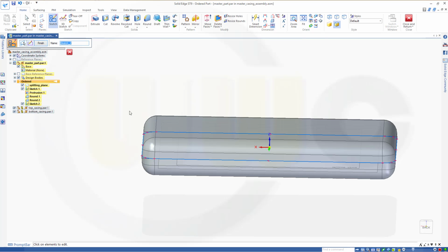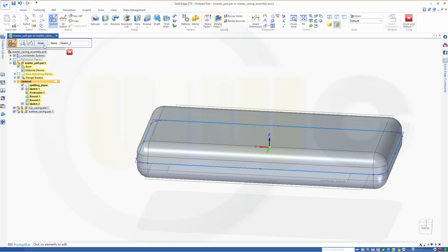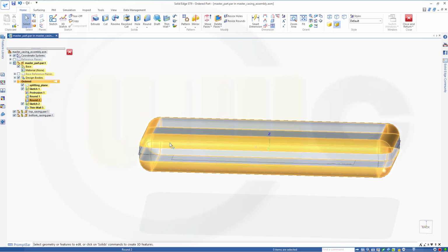and okay, now I want to shell this, cancel this out. So let's make a thin wall. Go to thin wall. I want to have it with 2 millimeters, and I need nothing of these, so I go for preview and finish, and that should be shelled.